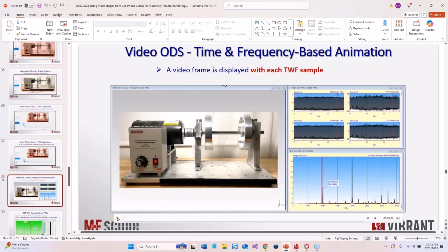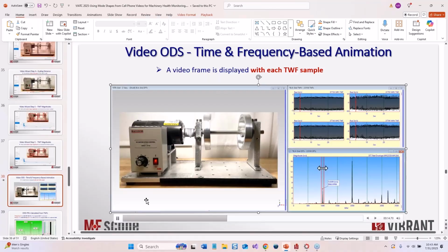And this is another video showing that there's no motion to the background, no motion to some of these other points that I'm not interested in. If I come down here and crank the amplitude, you can see very clearly the machine is bouncing around on its rubber mounts, and this is at 1,000 RPM, so that's what it was running at. It's kind of like a built-in tachometer. I know exactly where to look for peaks in the data.